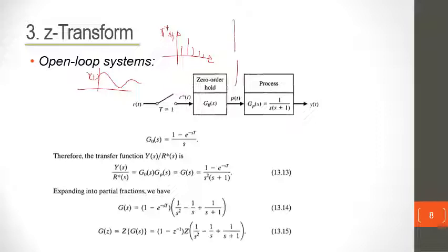And then with P of t, you would have the same samples here that follow the R star of t, but you will sample, hold, and then go to the next sample, hold, go to the next sample, hold, and so on and so forth. So it would be like this, some form of analog signal, but it will have these steps like that, and then the Y of t on the other hand will be something which we expect an ordinary analog signal to be. So these are the type of signals that you are looking at here.